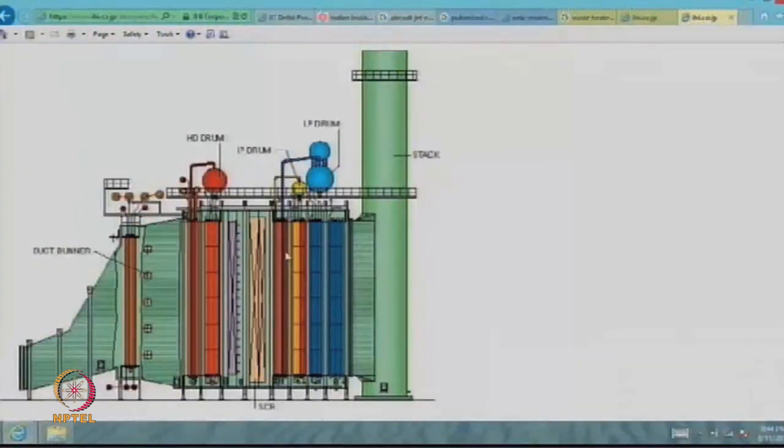So we have done the same thing that I mentioned there, but because of the engineering, the way it is done, these are a bunch of tubes whose design is different from each other, but each one of them does the same thing: the coldest water is being heated by the coldest gas, and we are trying to minimize the delta T as much as possible.